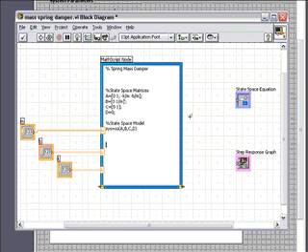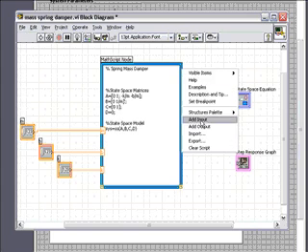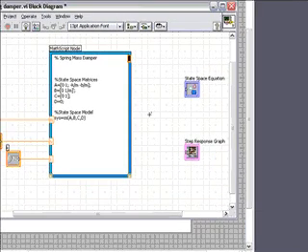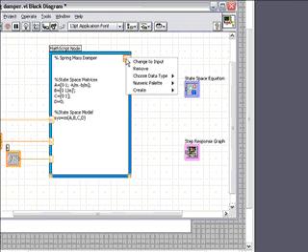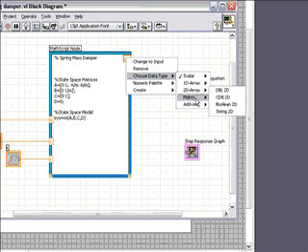And the next thing I'll do is I'm going to delete this line here as well. I'll have LabVIEW create the step response for me, so I won't be needing that command line. And so now I need to create an output node for the state space system model. And I'll right click and make sure that's represented in state space form.